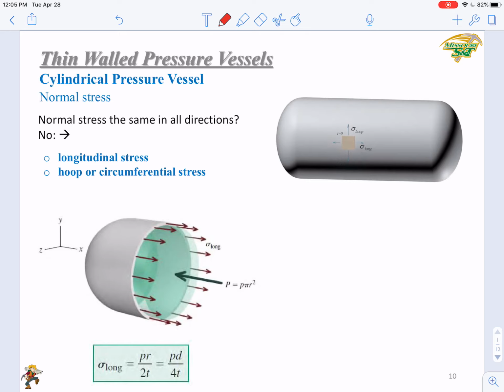So what is the projected area here in this case? The sketch is here. The projected area will be just the inner area of the circle, right? So that will be pi r squared. Then how about the wall area? The wall area will be a ring, right? This is pi (R squared minus r squared), or pi (R plus r) times (R minus r). Since t is much smaller than r, as we assumed and simplified in the previous derivation, this will be 2 times pi r t.